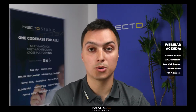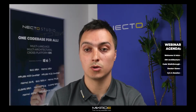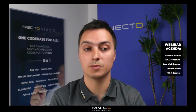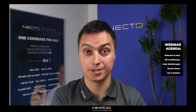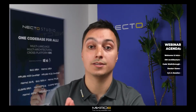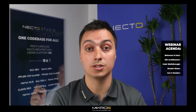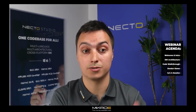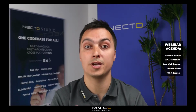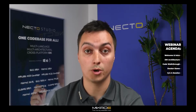I will show you how to approach this project methodically and professionally. First, you will see how to structure your code base into clear, maintainable modules. Specifically, I'm going to separate logging, connectivity, and sensors apart. Then I will use the conversion utility from the MikroSDK to prepare sensor data for transmission in a format suitable for LoRa.